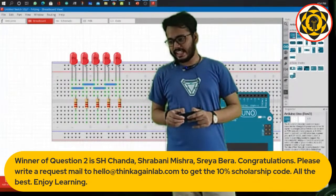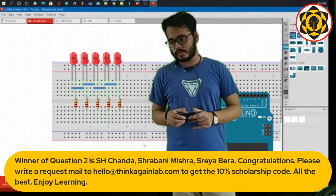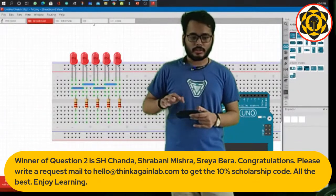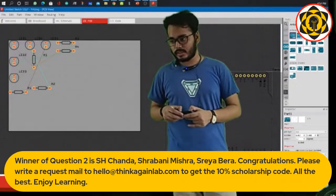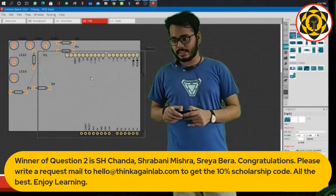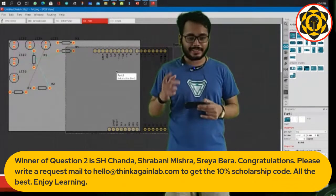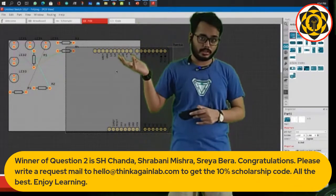Just take a bit of time into consideration that whatever microcontroller you're going to be using, you want to use the same one here as well. On one hand, this is cross-compatible. On the other hand, if we jump to the PCB view, we are not there yet, but just for reference, let me show you something. Since we have loaded a microcontroller, see, this stuff gets automatically loaded. So this is basically a blueprint of the Arduino. Now when we make a PCB out of it, it will automatically turn into a shield that you can directly place on the Arduino. You don't have to work out any wires or stuff like that.